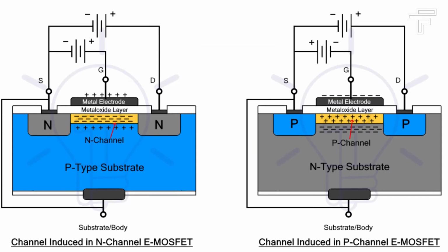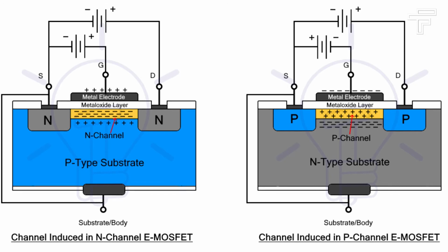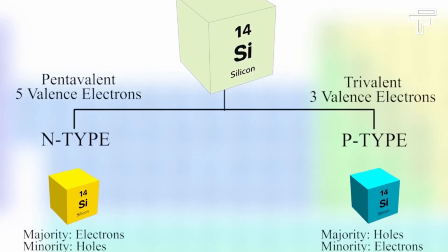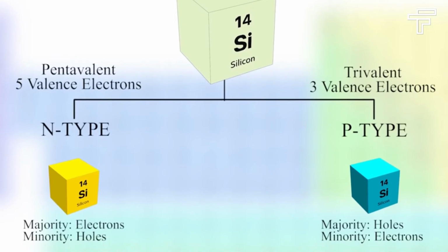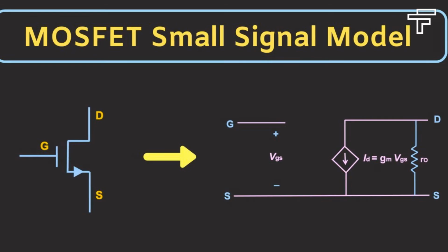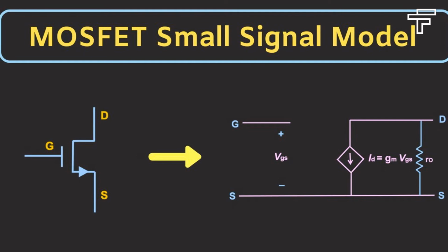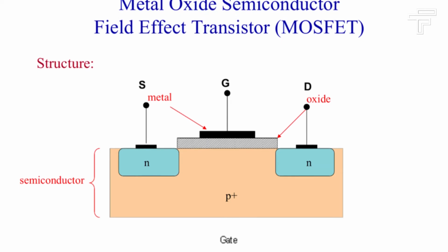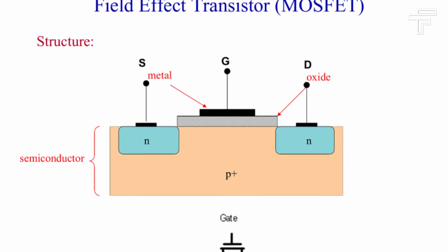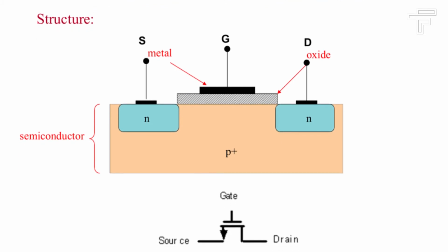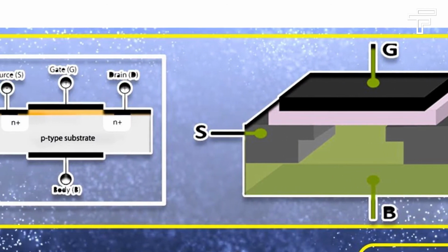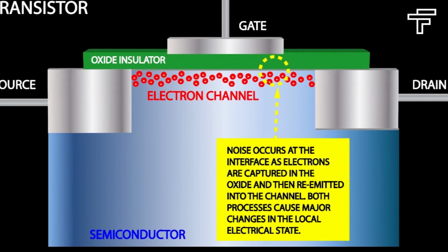The MOSFET is fundamental to building high-density integrated circuits, ICs, and VLSI devices since MOSFETs can be made with either P-type or N-type semiconductors. Complementary pairs of MOS transistors can be used to make switching circuits with very low power consumption. In the form of CMOS logic, the name metal oxide silicon (MOS) typically refers to a metal gate oxide insulation and silicon semiconductor. However, the metal in the name MOSFET is sometimes a misnomer because the gate material can also be a layer of polysilicon, polycrystalline silicon.